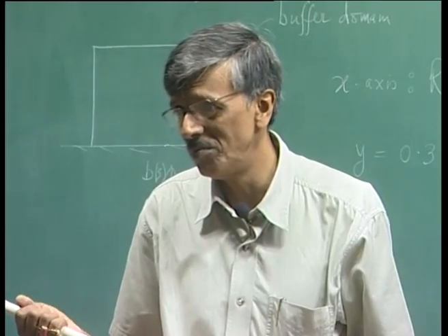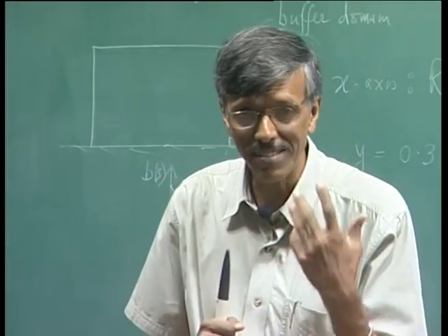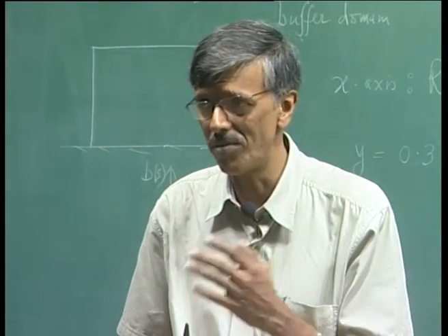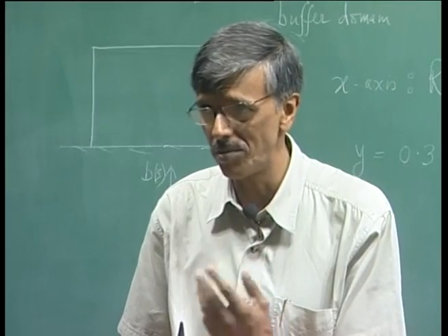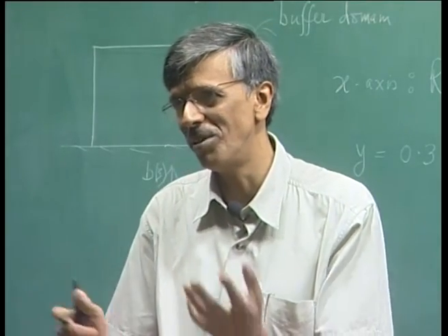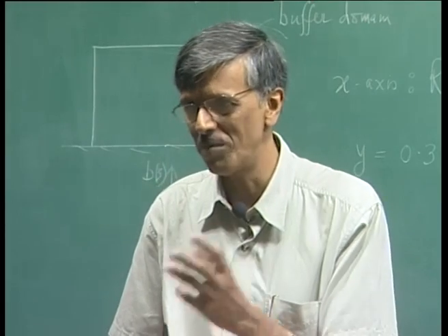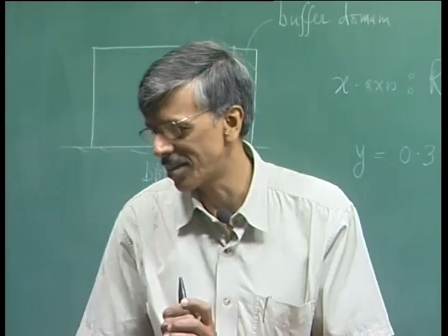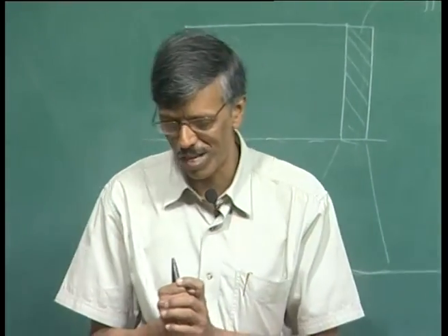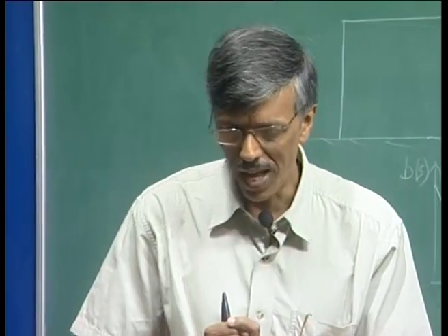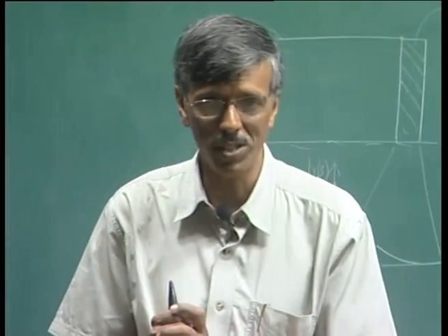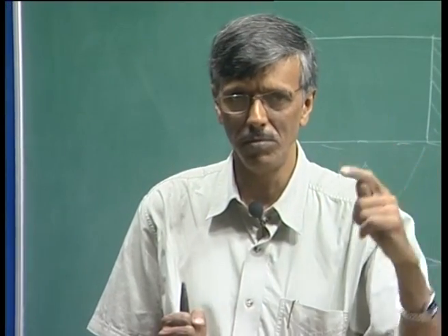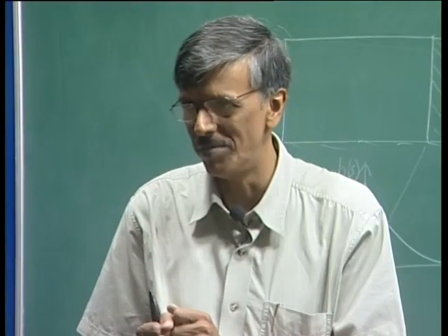What prevents us from going further? And this is exactly what Landau suggested. Landau suggested that after you have gotten the primarily unstable flow, you should study the stability of this compound flow, that is a combination of a basic flow plus a disturbance. If you look at it from the point of view of the Schubauer-Klebanoff experiment, then we are talking about what? We are talking about a basic time independent flow plus a periodic flow, because we have created a monochromatic wave.